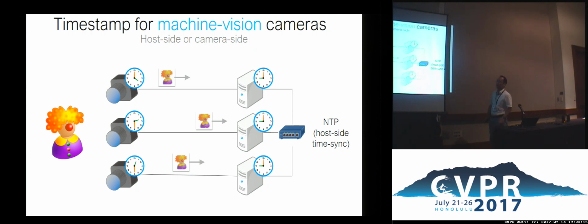And then the PC clocks are well synchronized, but basically this is not good enough in terms of the synchronization of the video frames, right? Because the image should go through the network and the host adapter, memory, CPU, and then after all these processings of your non-real-time OS, you can now check what is the time in your program, right? So you cannot expect how much delay you see here, frame by frame.